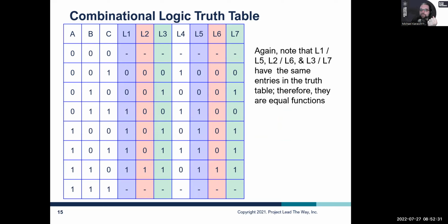We look at combinations, 0, 0, 1, which is a decimal 1. And we'd say, what should be lit up when we roll a 1? Turns out just that center LED, right? A 1 on a die is just that center LED. And so that one is a 1. The rest of them are all 0. That's what goes in this truth table.